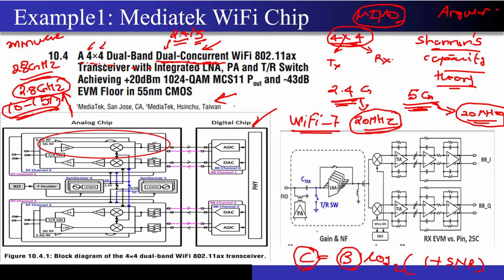So now again, if you look at the receiver chain, don't focus over here, because this is some next level stuff. You have low noise amplifiers over here, then you have the mixers. Now these mixers also are of 2 types: one is the voltage mode and one is the current mode. These mixers are actually dumping the current onto the baseband. So now I need a circuit which can take current as an input and produce voltage as an output. And what is the block that does that? There is a circuit called a trans impedance amplifier.